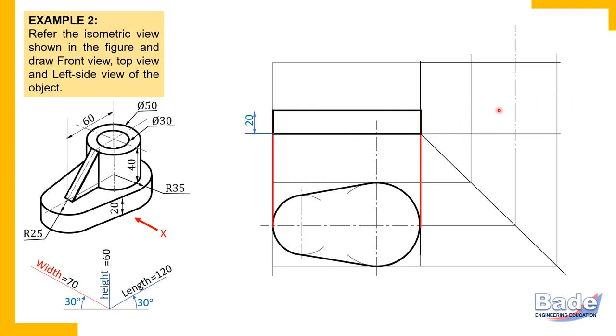Now let's complete the view of this plate in the side view. We already know it is simply a rectangle. A plate, if it is, say, a hexagonal plate or circular plate, shows its shape in one view. In the remaining views, it appears simply as a rectangular strip. So this shape in the top view, in the front view it is a strip, a rectangle. In the side view also you will get that rectangle. Which two dimensions do you get in the side view? Height 20. You can measure it independently or you may draw projectors. So I have transferred the height of 20 millimeters. But as I have told you earlier, for smaller details I prefer measuring independently.